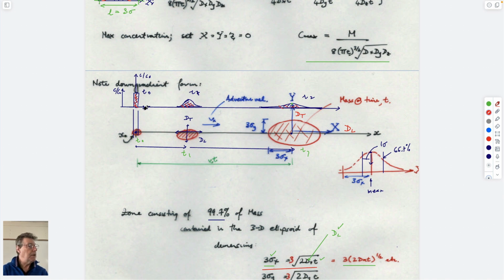If the same amount of mass is present in the water but just spreads out at a lower concentration, then you'd think that the areas of these distributions would be the same whether upstream or downstream. That assumes that the same amount of mass stays in solution, but it's flowing past porous media, so it may get pulled out of the fluid and attached by sorption onto the porous medium, and if that's the case, then you'd expect that this area under the curve would decrease.